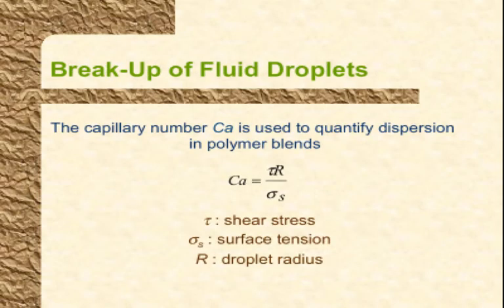So that is as far as some ideas behind, depending on what you mix, answering the question of how much to mix and what shear rate to mix at. Depending upon that answer, you can go to different types of mixers, and depending upon the geometry, you can adjust the shear rate. And a mechanical engineer does all of that.